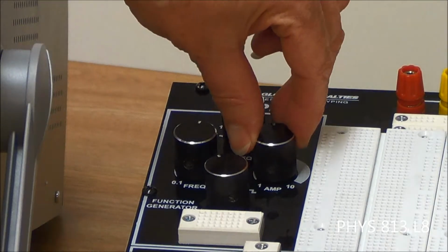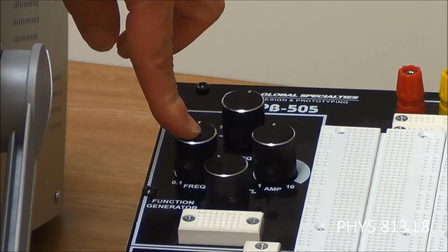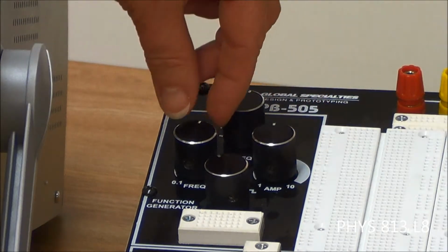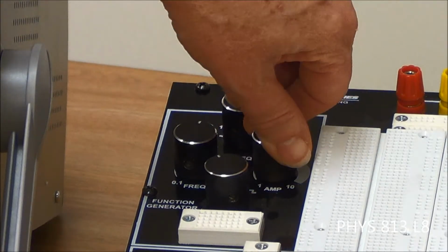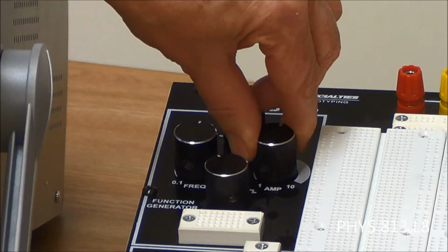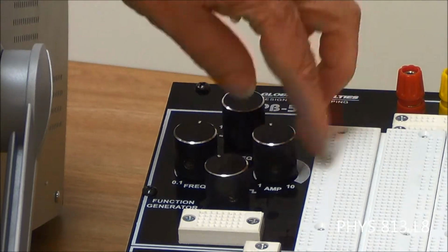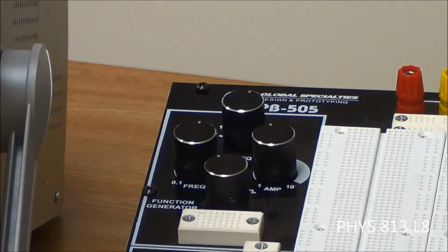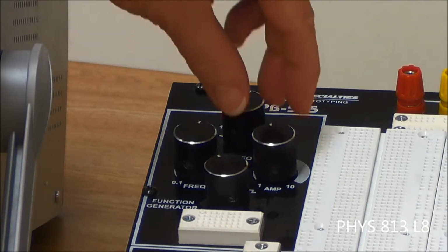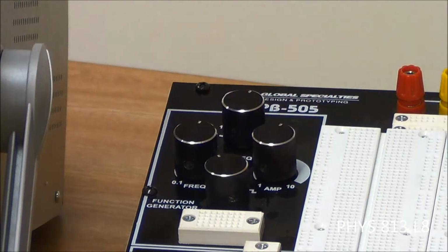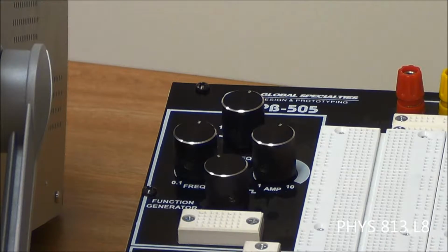Okay, then over here to the right of the continuous frequency knob or dial is another one. It goes from 1 up to 10, and those are sort of arbitrary numbers. It's labeled AMP for amplitude. It changes the voltage, so you can get various voltages if you want a large voltage or a smaller voltage. And that, in combination with our volts per division, you can produce the voltage that you want.